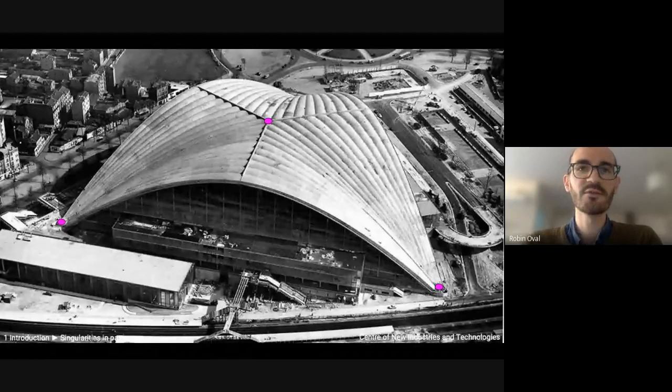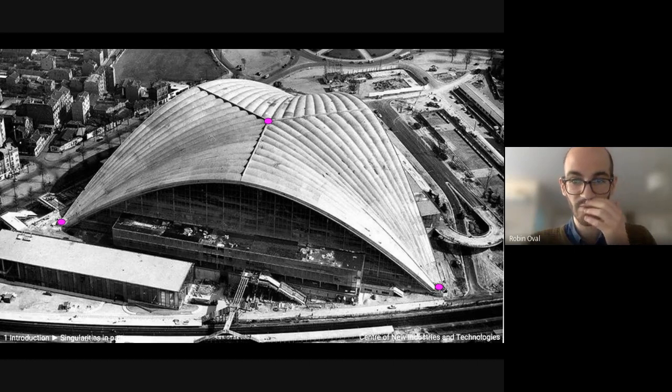So you can see that you have this regularity in the corrugation patterns, but what's more important are these irregularities that allow you then to break this pattern into different patches and to orient these stiffening corrugations in the right direction, so to carry the loads towards the support. And if you don't make a relevant choice of singularities on this design, then you will not be able to bridge this span.